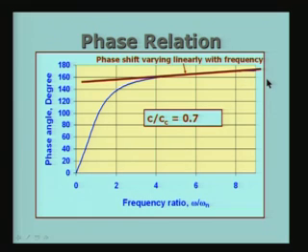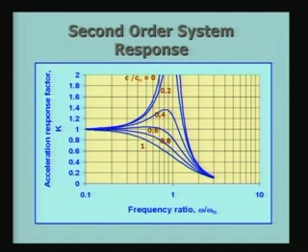This is another second observation we are going to make. So, how these are going to be useful in practice, we will try to look at a little later. The third one is the acceleration response factor k, which is the expression number 3 which I gave on the board. What I have done is I have plotted the acceleration response factor k versus the frequency ratio, but I have used a logarithmic scale on the x axis, so that the figure looks slightly different from what it was earlier, and you will see the important thing here.